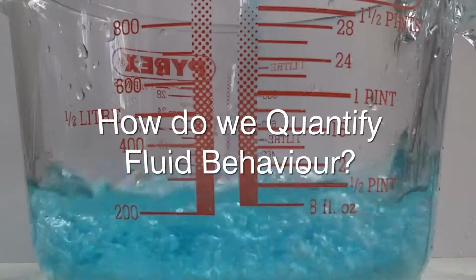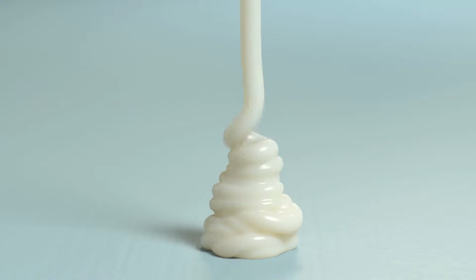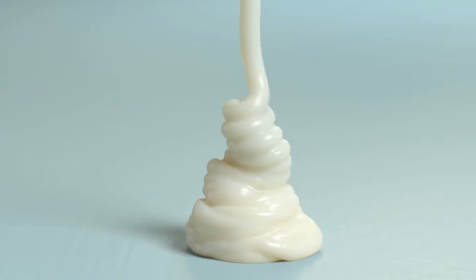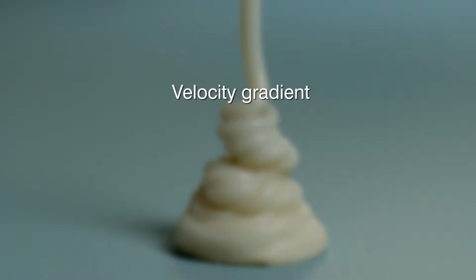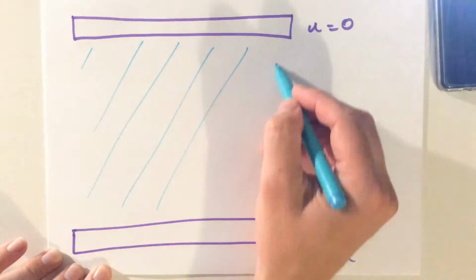How do we quantify fluid behaviour? Viscosity is the most important property affecting flow behaviour of a fluid. It's determined by relating the velocity gradient in fluids to the shear force causing flow to occur. Consider a fluid sandwiched between a stationary plate and a moving plate.